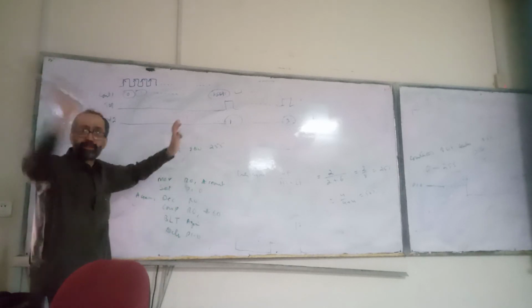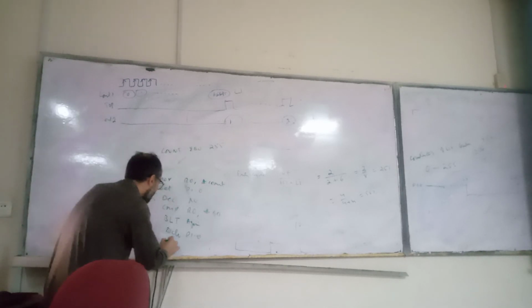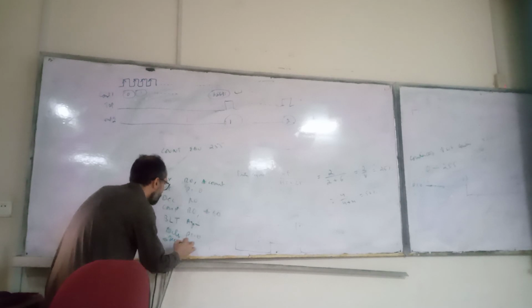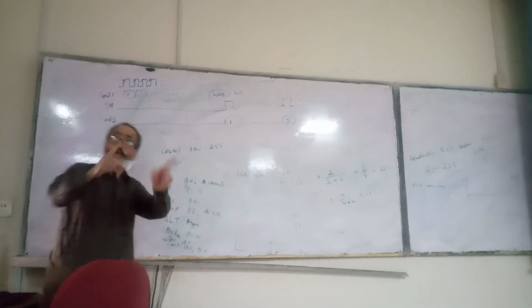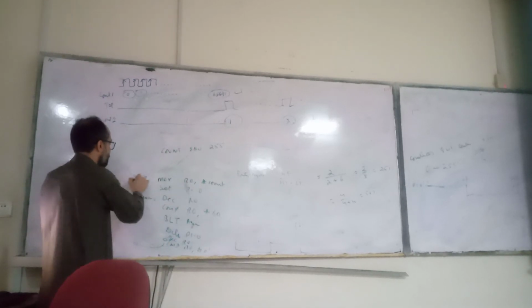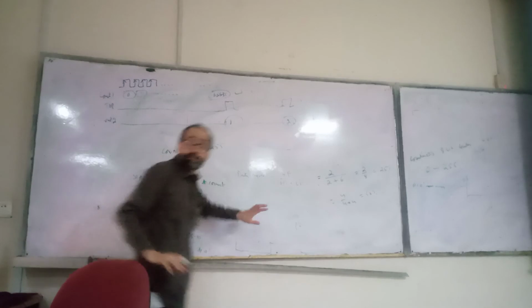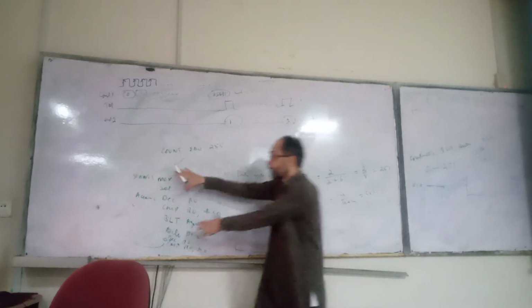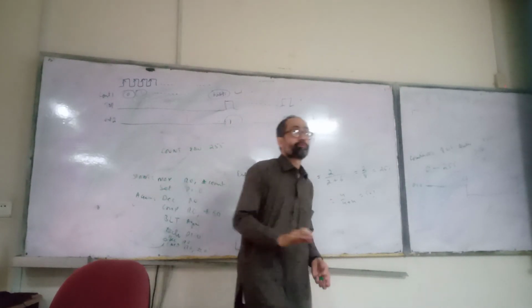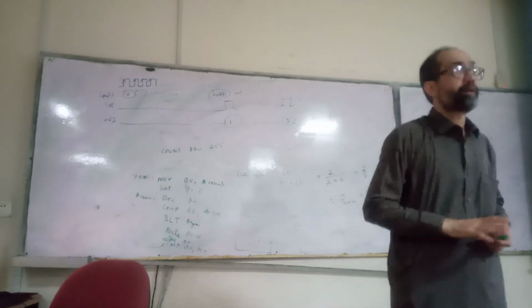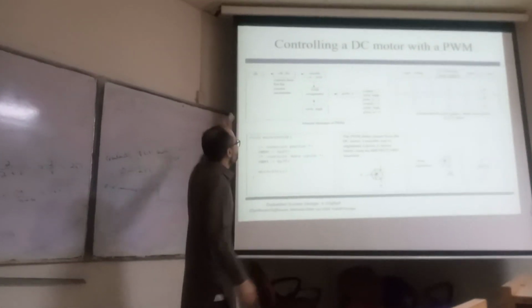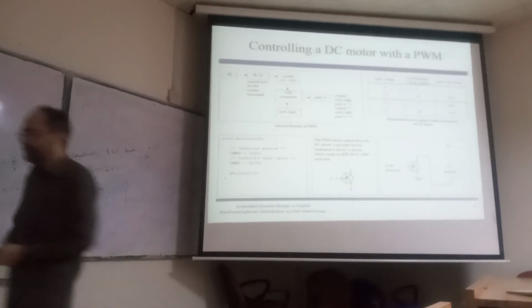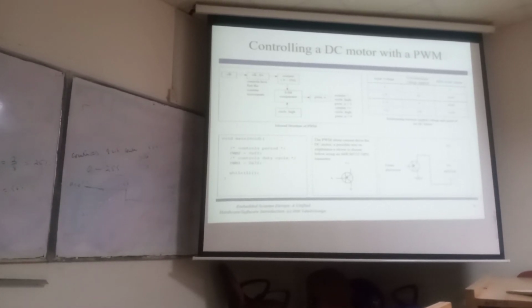A lot of possibilities are there. This is one of the possibilities. Then you decrement R0 and compare R0 with 0. When it reaches 0, you just move to start. You can have a small assembly language program. This is just an overview of how you can write a small assembly language program. You can also use a built-in counter within the microcontroller or microprocessor, and the built-in counter will serve that purpose for you. So this is the way we can generate a PWM signal.